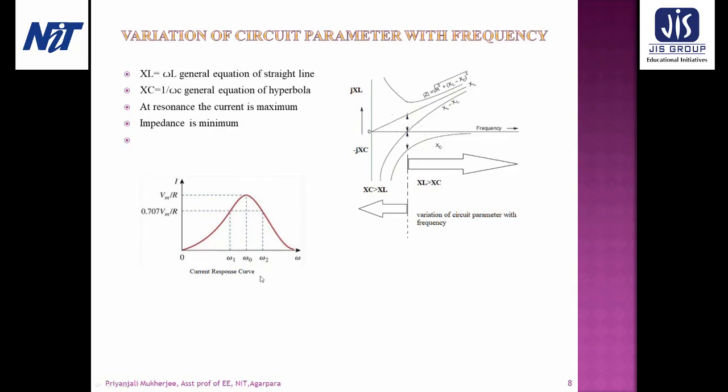This curve is asymptotic in nature. At frequencies lower than the resonating frequency, the circuit behaves like a capacitive circuit, and at frequencies higher than the resonating frequency, it behaves like an inductive circuit.